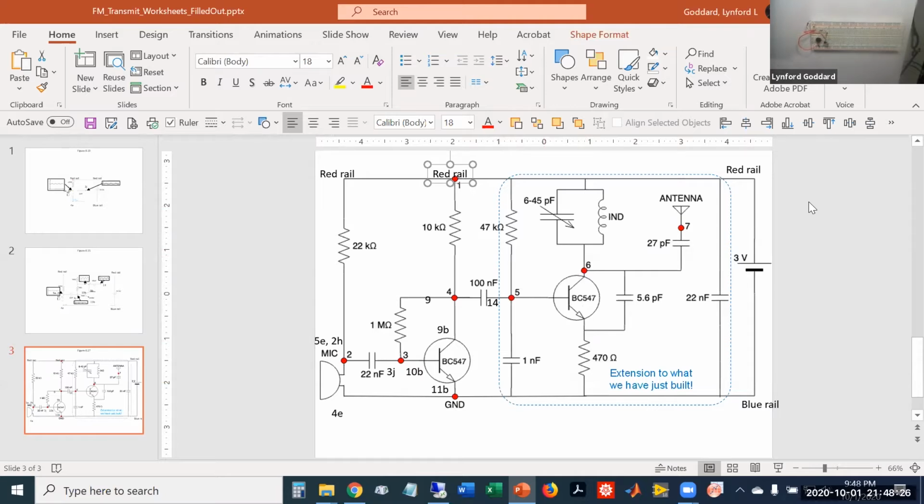So we take out our next transistor. So we have this element. And on the board, I'm going to go with the collector in row B. And I'm going to do 18, 19, and 20 for the transistor.